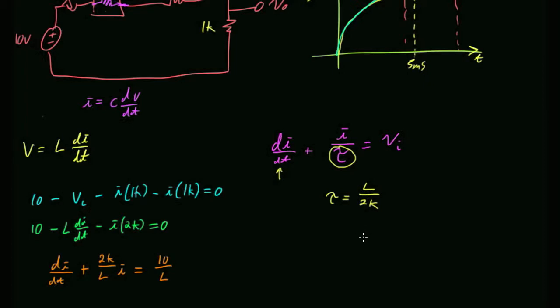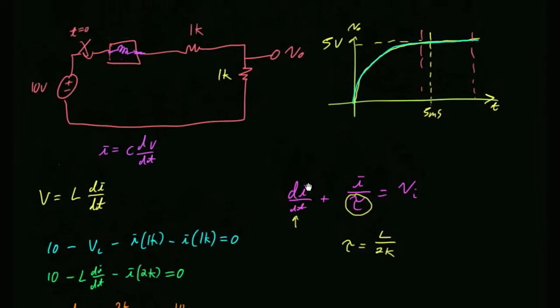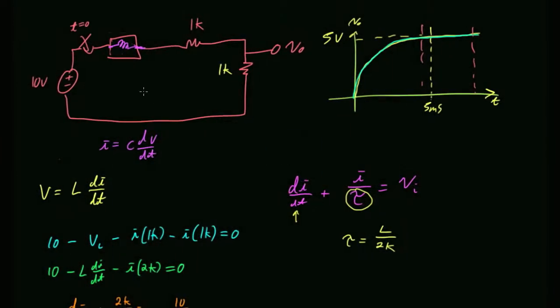Yes? Can we say if we place a capacitor there, we would have a high-pass filter, and the graph doesn't look like a low-pass? You're saying if you put a capacitor here, it would be a high-pass filter. That's correct, and the graph is clearly a low-pass filter. Therefore, it can't be a capacitor. Absolutely, that rationale works perfectly.